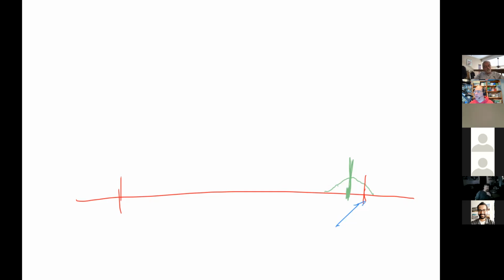So that's why it's important to know. That's another reason we're taking this class. That's another reason we get licensed. We are assumed to understand that what our signal looks like determines where we can put it. So if we were to do lower sideband and the signal looked like this, only half of it, would we be legal or not? No. Yeah, our signal is completely inside the red lines. If we were to switch to the upper sideband up here, whoops, our signal would now fall partially outside. And then we would not be legal.